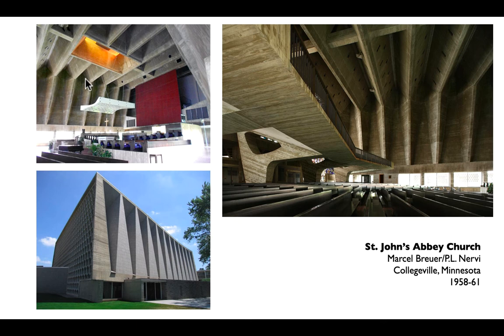And this, of course, is all one monolithic structure, right? The column sort of fades into the girder structurally through that corner joint. But everything, because it's folded, has a depth that can be tuned to whatever the structural need is. And you can see that the structure is a consistent depth, or the fold is a consistent depth going across the top. And the columns then taper as they come down to what are essentially pin connections on the transfer girder below.